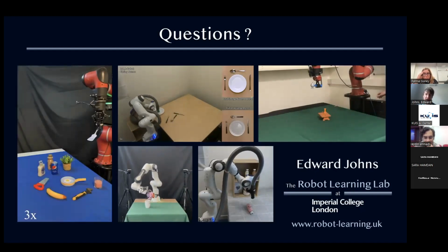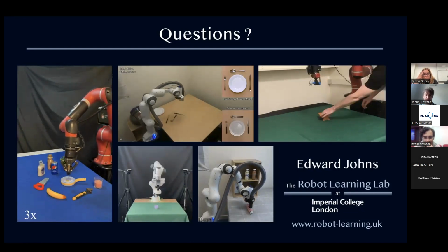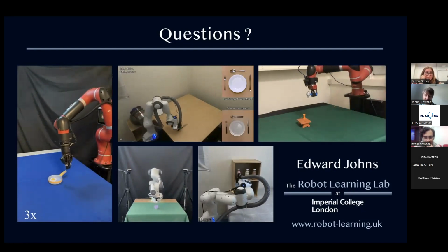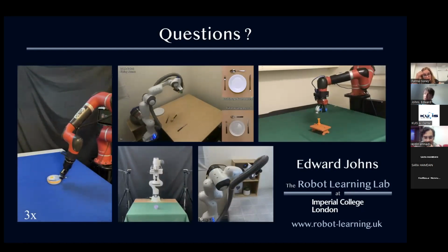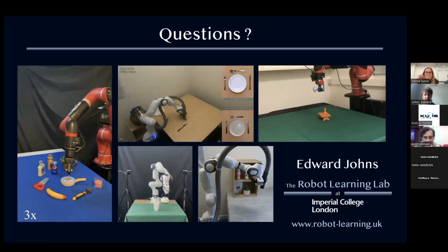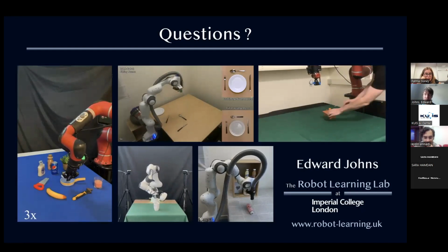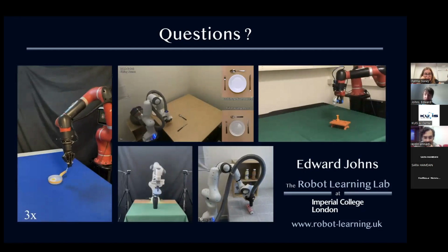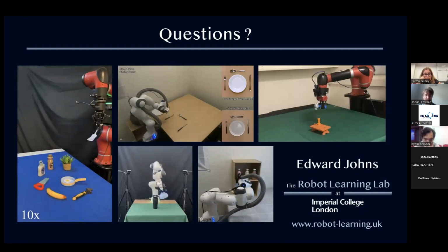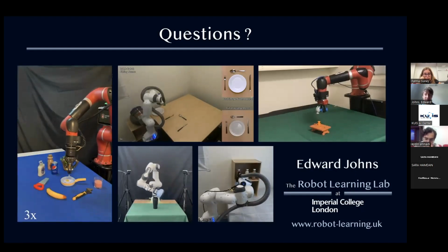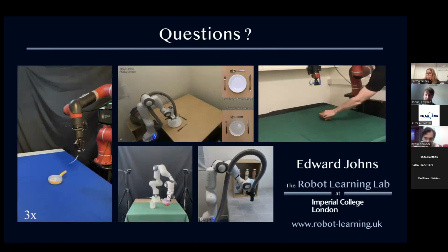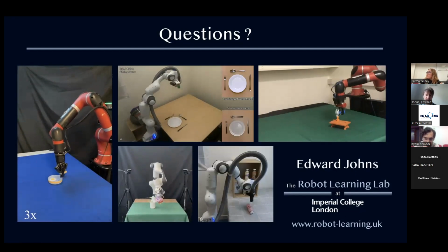If you want this to be done in an unsupervised manner where the robot simply takes the demonstration and then adapts that data according to what it thinks is an optimal solution, there's a risk that the robot would end up assuming things about the task that are not actually what the human wanted the robot to do. For example, you could add in smoothness to make the trajectory very smooth, but maybe actually you needed this very complicated, wiggly, jerky motion because that's just what the task requires.